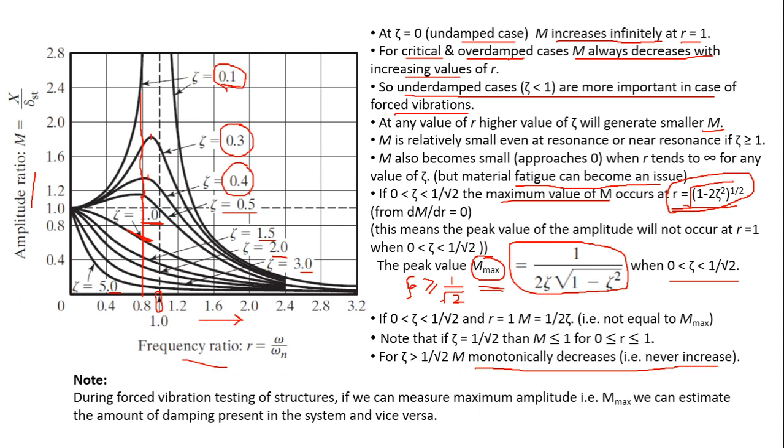And as far as the critical and overdamped cases are concerned, they are already heavily damped systems, so they don't show any peak in their magnification factor. They continuously decrease as r increases.